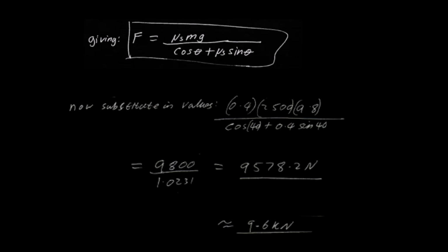Now the important thing to remember here is we've done everything in terms of the force and re-expressed it in terms of our frictional force and included everything in one expression. The most common error here is people doing F equals ma, comparing that simply to mu mg and then trying to press on through. That would be a very difficult way to solve this problem, and as such this is the recommended methodology.